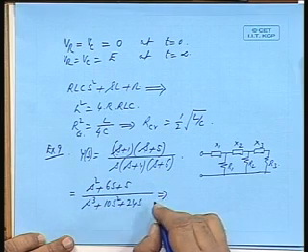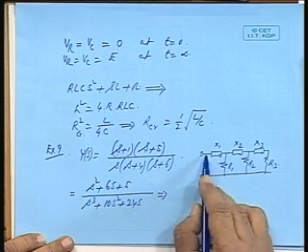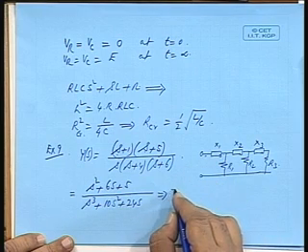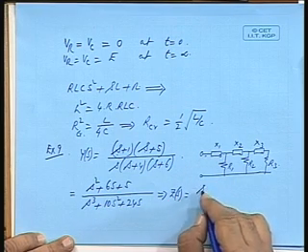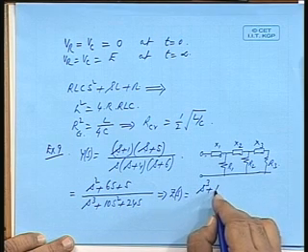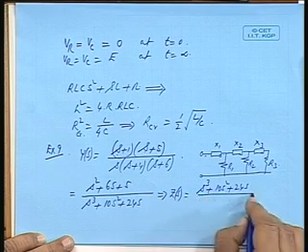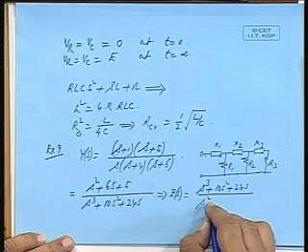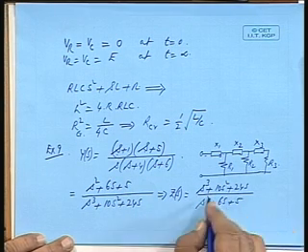So, correspondingly Z(s), you see the first element, if it is present, then it has to start with a Z(s), which will be (s cubed plus 10 s squared plus 24 s) divided by (s squared plus 6s plus 5). Okay.